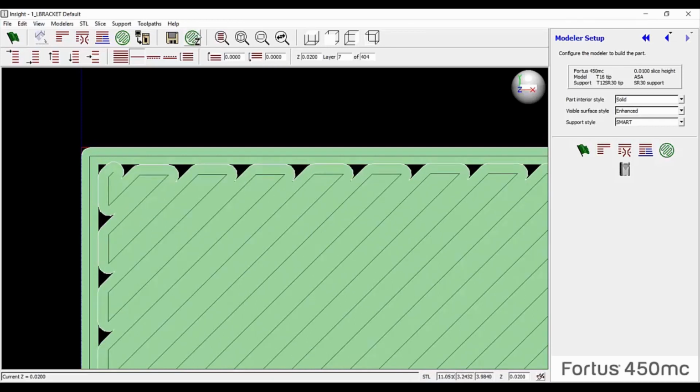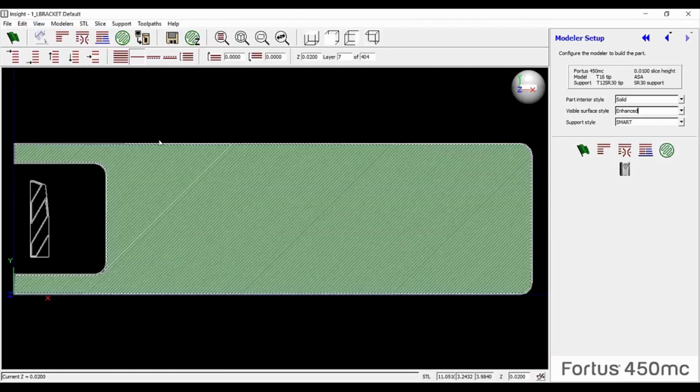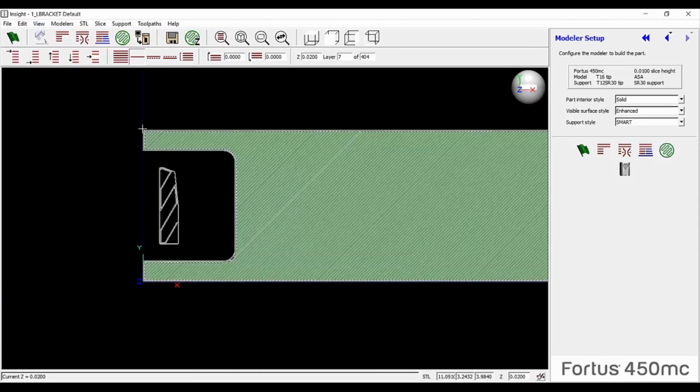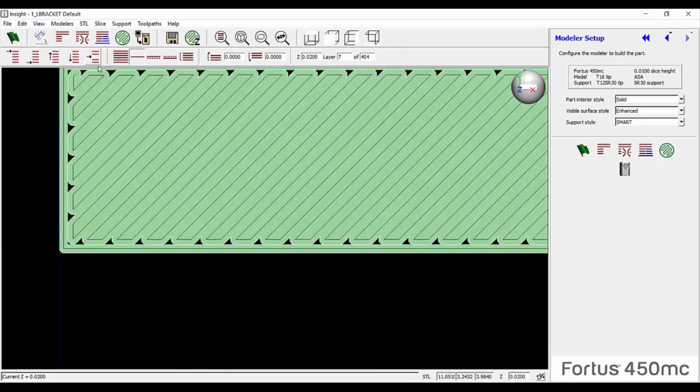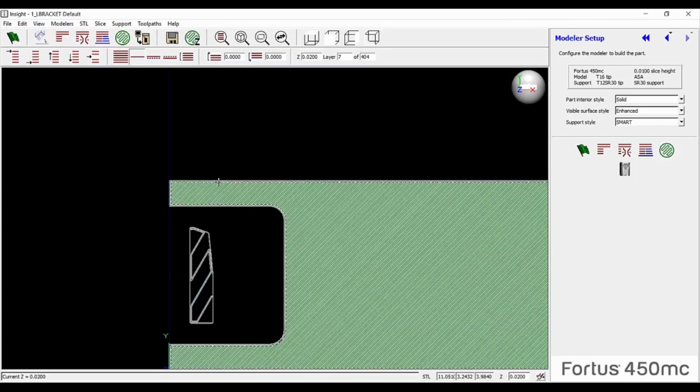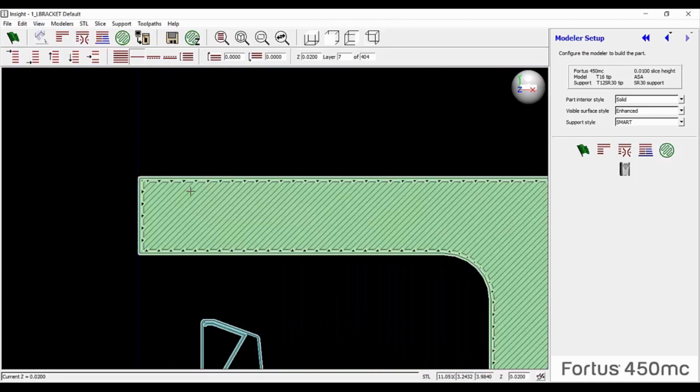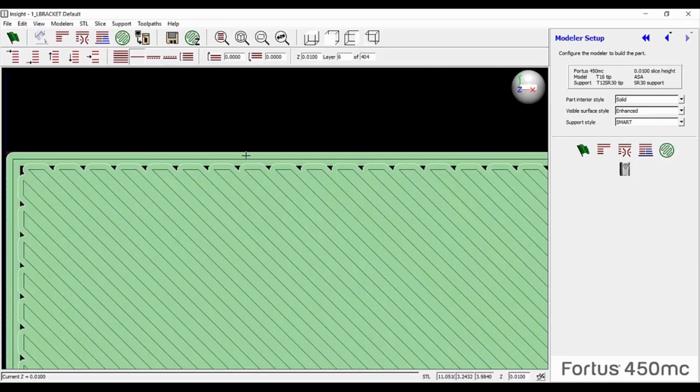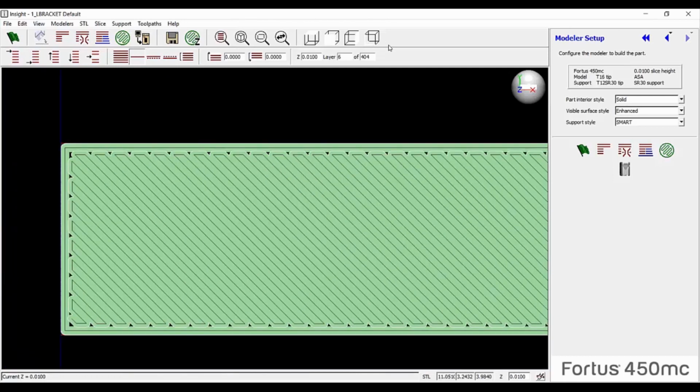Like I explained in the intro here, that's done by turning the drive wheels faster on the internal layers that you'll never see. So you're building the part faster that way. I always use an analogy of a coloring book. It's like doing a coloring book but having a wider pen. It doesn't take as many passes to fill in a specific boundary. And our bottom actually looks better because of it, because we have a smaller pen on the first and last page of that coloring book, the pages that somebody's actually going to look at.